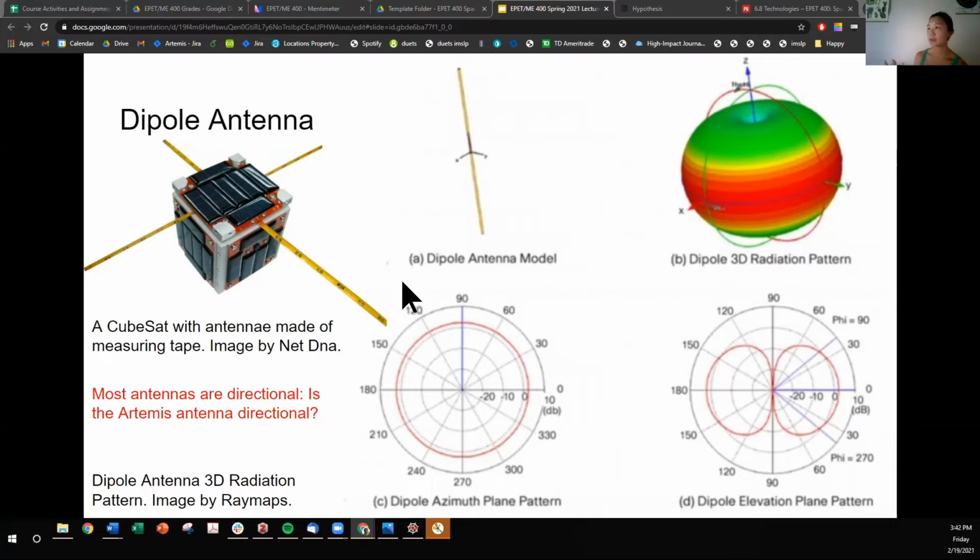When it comes to CubeSat technology, it could be that the CubeSat doesn't have an ADCS or some kind of pointing control inside the satellite due to volume or power constraints. So it could be a better idea just to make it as simple as you can. To do that, you want to incorporate an omnidirectional antenna. Keep it simple, stupid is the phrase.